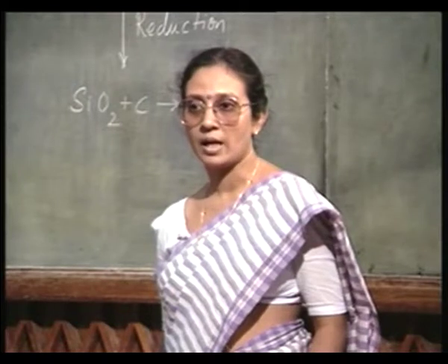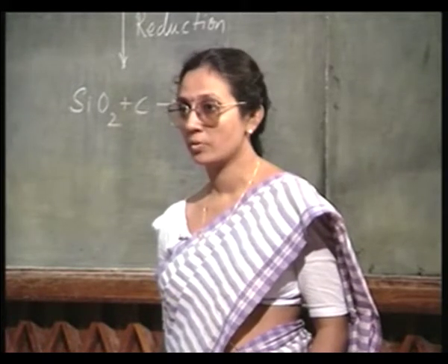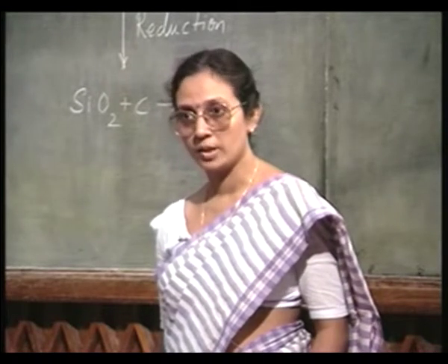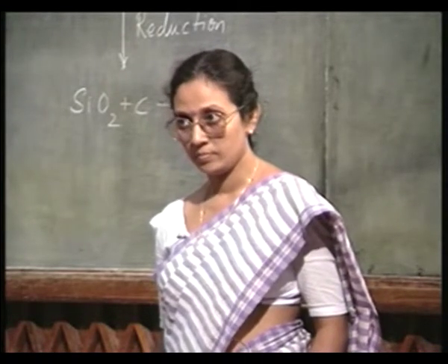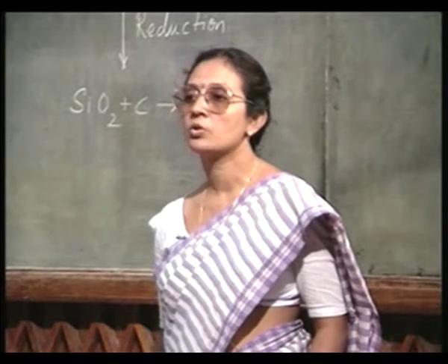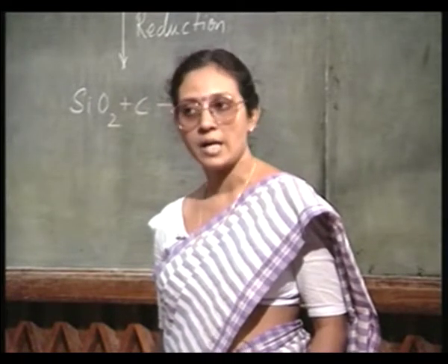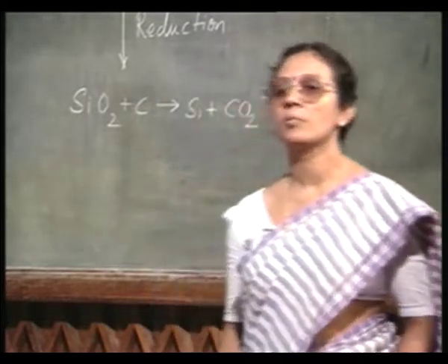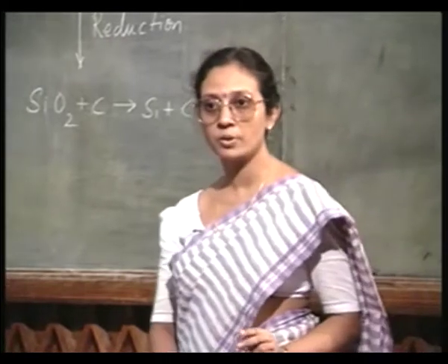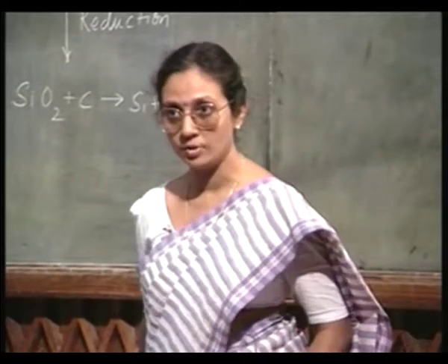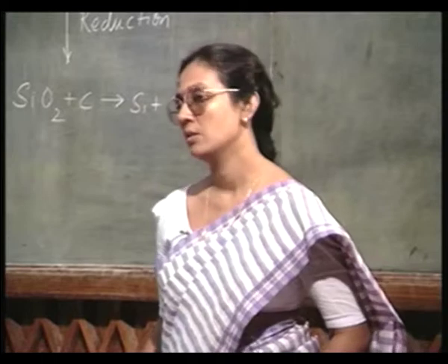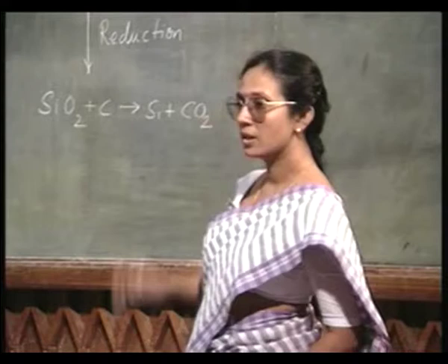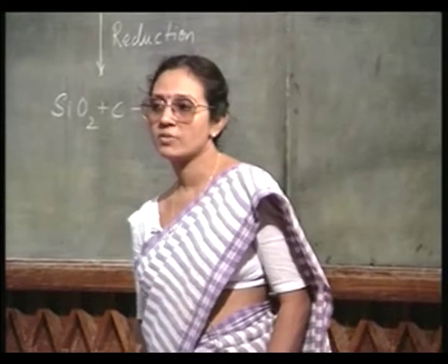So, the material you have will be doped p type, quite highly doped p type, because of the presence of aluminum. So, it becomes difficult to control the conductivity of the as grown silicon. That is why it is not really a commercially viable process, although theoretically speaking this is also possible, a metallothermic reduction of silicon. So, commercially almost every single crystal silicon that is grown comes via this route.